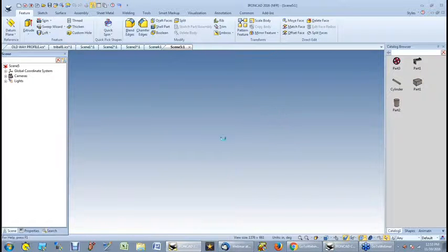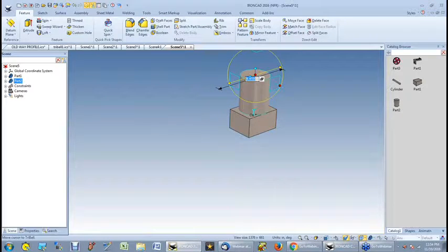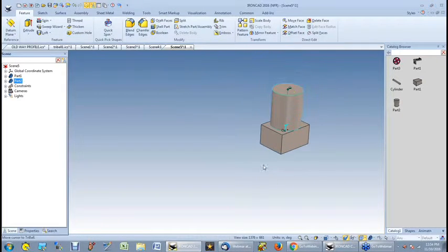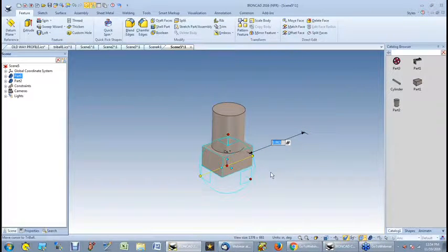So now if I take the block, drag it, take the cylinder, touch it on top of it, highlight the cylinder, turn the tri-ball on, it's all locked together. Same at the bottom. Turn the tri-ball on, it locks together. So that's how quick and easy it is to make attachment points.